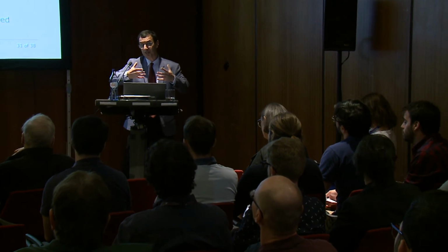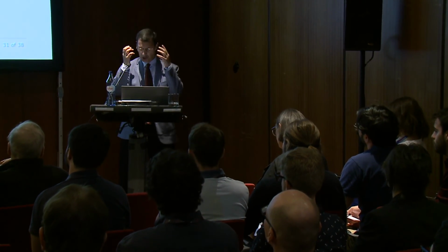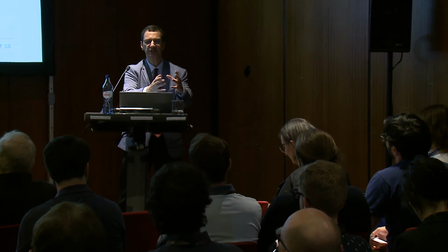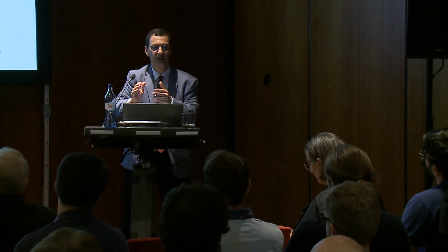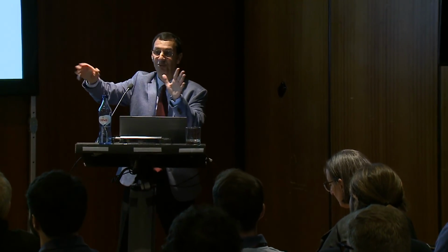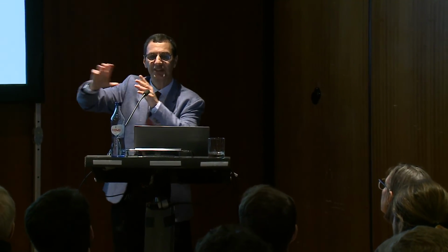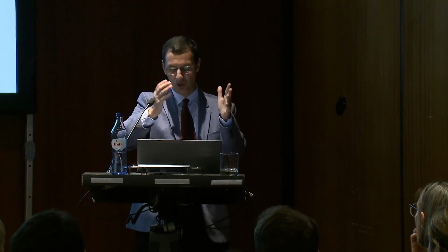So this is the process. You need to simplify to get close to it. And once you get it, you say, the rest doesn't matter. The rest is just, I don't want to say noise, but the rest is something that is cluttering your mind and you don't see it. So first thing you do is you get a complicated circuit, you see what is really doing the work. And I find that in many of the circuits, it's the short circuit current and the output resistance that is doing the work. And for this circuit, you can analyze it using feedback.